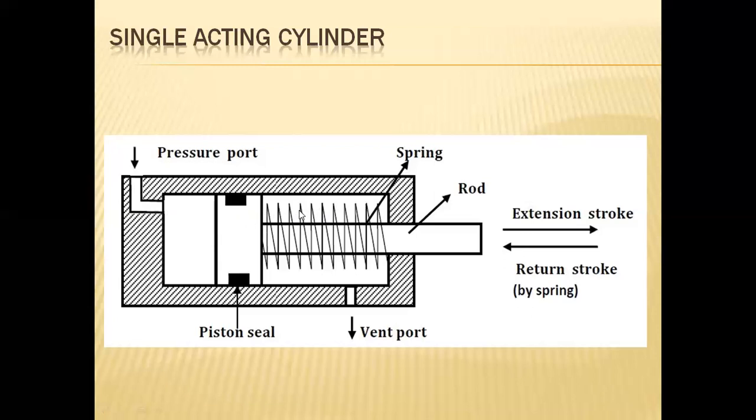If the tension of the spring has been crossed over by the pressure of the fluid in the hydraulic case, then the pressure entering is much higher than the tension, and the compression will start within the spring, and it leads to the extension of this cylinder piston.